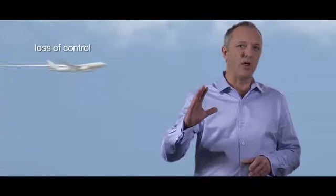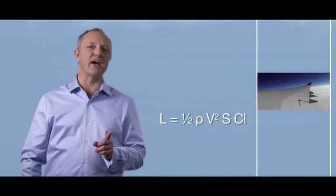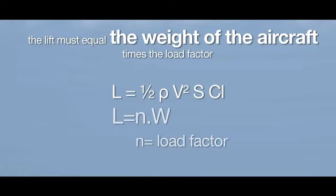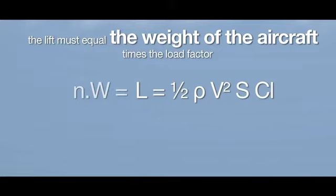A stall is characterized by a loss of control, then by a loss of height. A wing generates lift, where L equals 1/2 rho V squared S CL. The lift must equal the weight of the aircraft times the load factor. L equals N times W, where N equals load factor and W equals weight. The general lift equation becomes N times W equals L equals 1/2 rho V squared S CL.